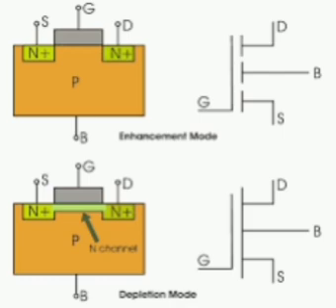The difference between PN diodes and Schottky diodes can be tabulated. The forward bias needed to make the device conducting, the cut-in voltage, is large for a PN diode, while for a Schottky diode the cut-in voltage is quite small. In a PN diode, the reverse current is due to minority carrier diffusion to the depletion layer and has strong temperature dependence.